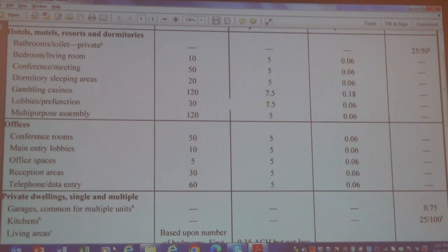So that argument, Mark, sorry to interrupt, you take it with the architect from the beginning, not on the inspection. It's an easily misinterpreted code because they see the word office and they assume that's office, but it's not. It's really more of the data entry or telephone use. And that population, 60 per 1,000, is more realistic. Or if they want to go by the count of the actual furniture count, I allow them to do that.